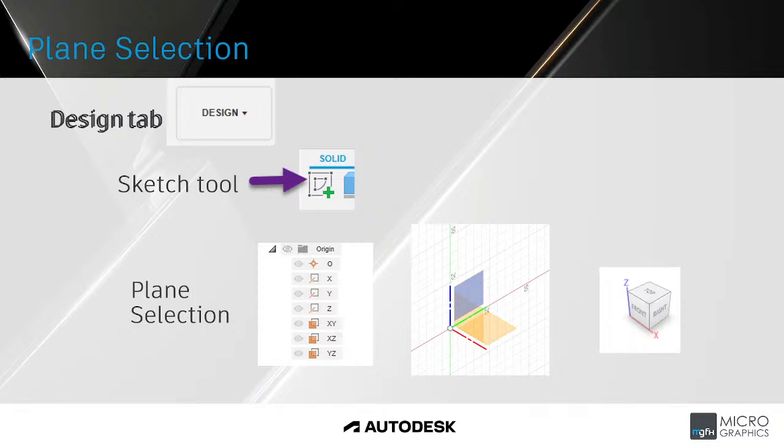The XY plane will be the front view, the XZ plane will be the right view, and the YZ plane will be the top view. This is in conjunction with the view cube. Views can be changed on the view cube. If you simply right click on the view cube, scroll down to the Set Current View As option, and you will have the selection of front or top view.